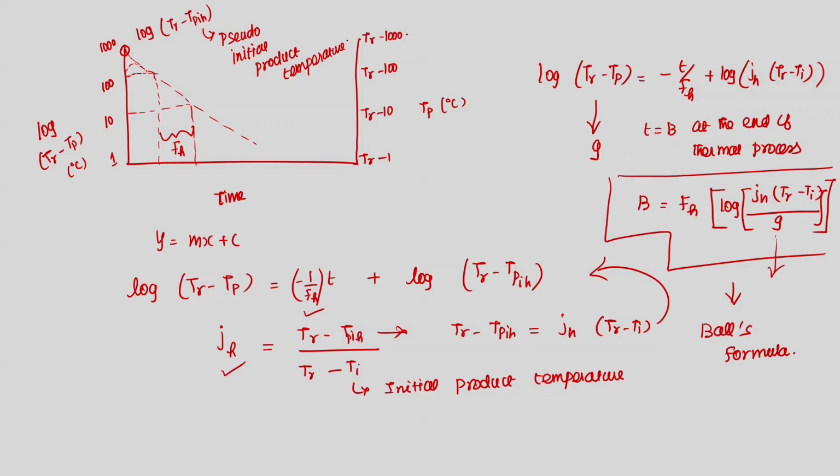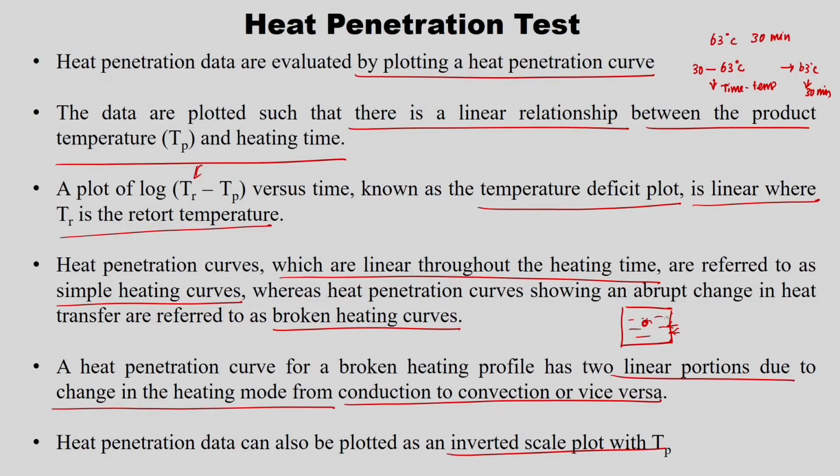And you also have to calculate the equivalent F value for thermal process establishment. That can be done using F of reference at Z, which is the integral from 0 to t of 10 to the power of (T minus T reference) upon Z into dt, which is nothing but minus D reference into log of N upon N naught. Okay. So, this we have discussed, this is what I just explained to you.